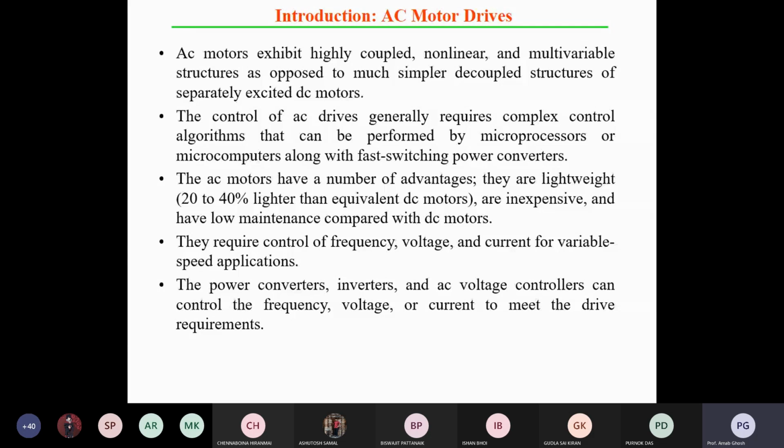So, I am telling you, the controlling condition in a DC motor is easy compared to AC. That's why you are converting the 3-phase by using Park transformation, Clarke transformation. A lot of transformations are there by name. So you have to convert ABC to DQ0. If you convert from ABC to DQ0, then the controlling in the D axis and Q axis is quite easier.